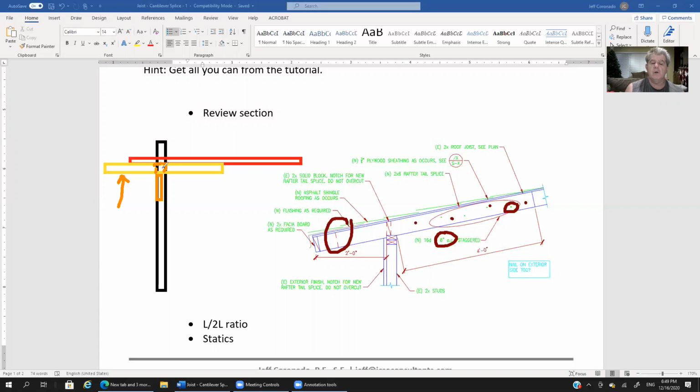I don't really know what the contractor would prefer to do. I don't know if they would prefer to just knock out that block and put in a new block, or do what the engineer is suggesting here, which is to get real surgical, if you will, with very small hand tools and cut a portion of this block out, so that they can slide in the new splice. But I suppose this is okay. And if the contractor comes back and says, hey, do I need to do it this way? Do I need to saw cut that, I'm sorry, not the rafter, the block, or can I just remove it and place a new block? Sure, if they ask us that, you can do that, right? But I suppose there's nothing wrong with how the engineer is specifying this block to be treated.